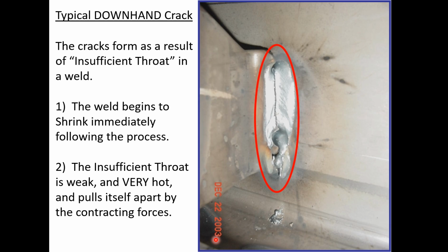Now, just before I carry on, this particular weld, I'm looking at it and I'm thinking to myself, if a person could get a grinder in there, I'm only saying this because it would again be at the discretion of your quality, but there's nothing contaminated about the material. Their problems do not extend into or outside of the toes of the weld, so the weld is intact. There's no metallurgical issues with it from a contamination point of view. I don't see anything. So if you could get a grinder in there, grind some of that material away so we're not worried about the compromise in penetration, open it up, and replace that weld. Again, quality's discretion. But I would consider it.